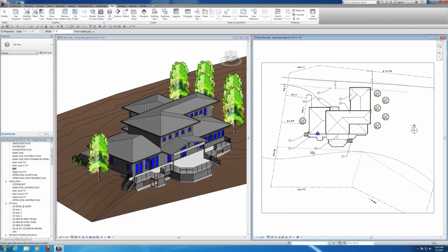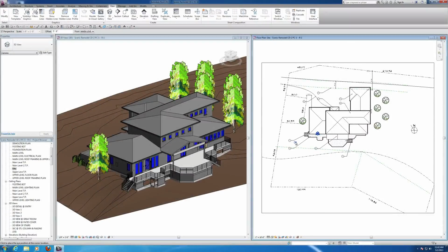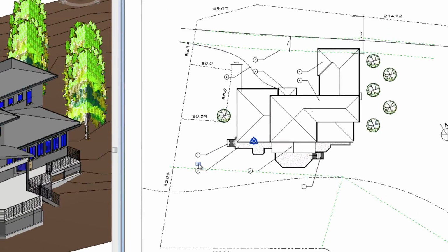If I come back to my site plan and I'm right here getting my view, you're actually off the ground. And the computer doesn't care, it just has a reference point where it's going to put the camera, which is 5 foot 6 above that main level, and the direction that you're going to shoot. Okay, so let's do one that way. So I'm going to be off in the backyard, off to the side, and then I click.